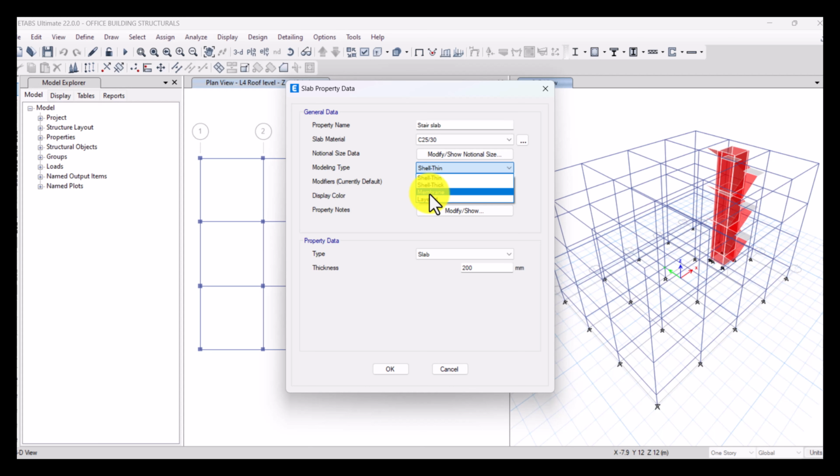It is used, let's say, if you're designing trusses and you want to put something to appear like a roof sheet, whereby we all know that roof sheets don't take up loads. They are just surfaces or membranes. So all the loads imposed on them, like wind, are supposed to be directly taken up by the trusses into supporting beams, then into columns.